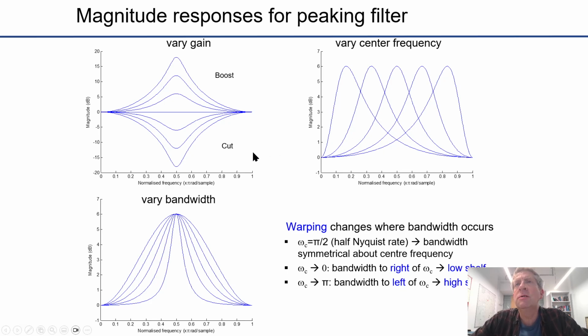Notice there's what's known as warping. So it's best seen when varying the center frequency here. Look at this curve where the peak value is around 0.15, maybe close to 0.2, but it very sharply goes up and very slowly goes in the other direction. And you see it loses its symmetry more and more when the center frequency is far from the mid-range of possible frequencies.